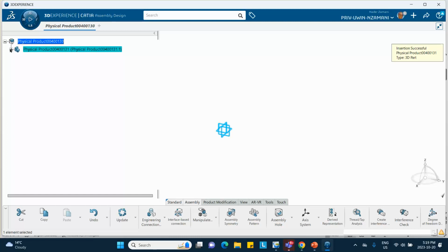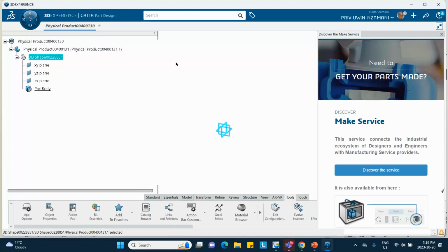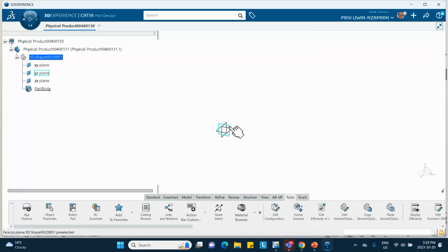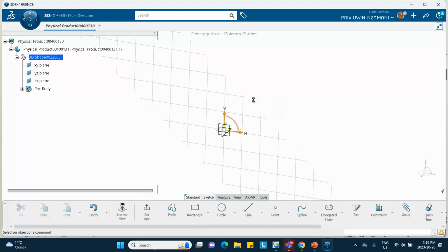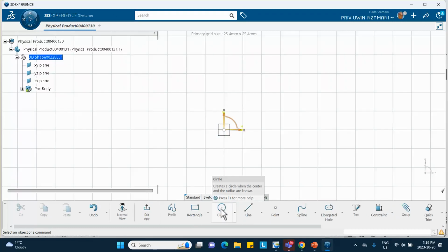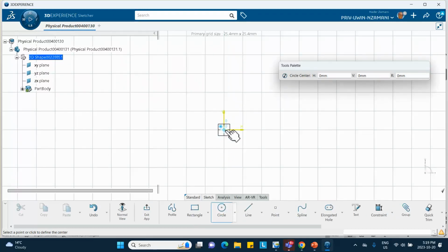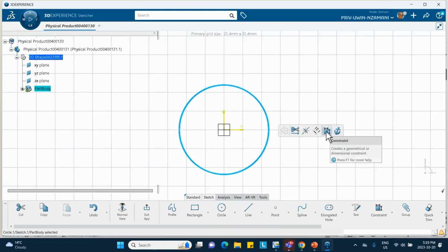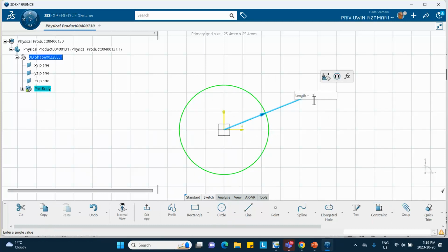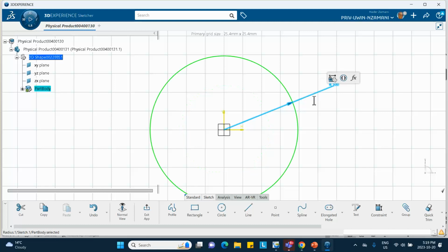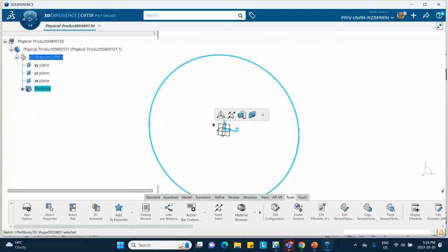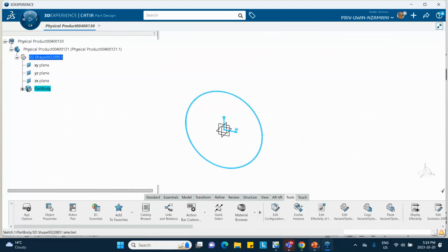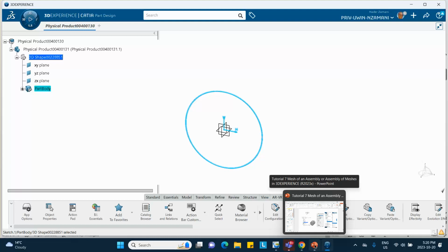Let's call it like that. But I will not change the name of it. I'll just leave it the way it is. Okay. So we want to make it. I double click on the 3D shape. And on that vertical plane, I will sketch a circle of radius 100 millimeters. So this is going to be 100 millimeters. Exit